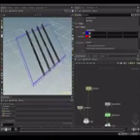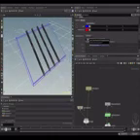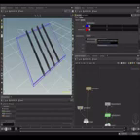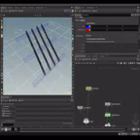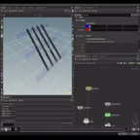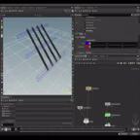And to solve this, you have to check this create convex hull for a set of connected primitives. Perfect. Let me see if I check box option. Now let's leave it as convex. So this is gonna work fine.